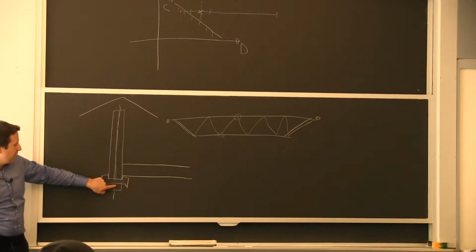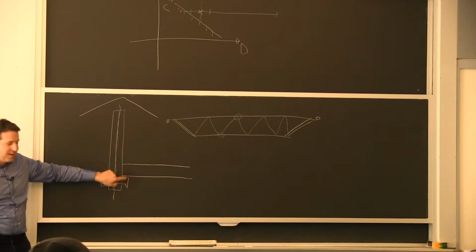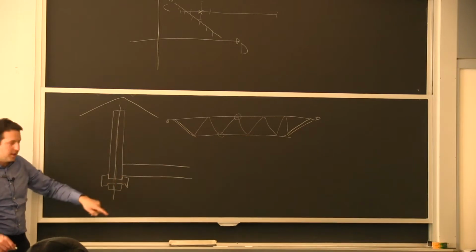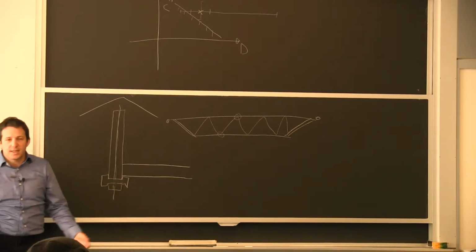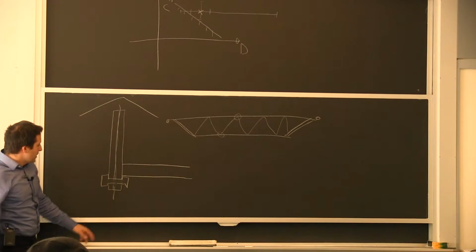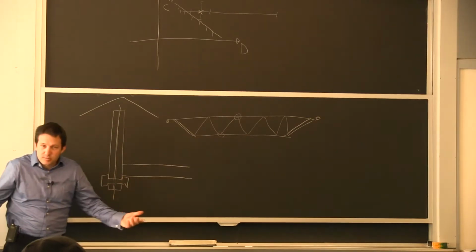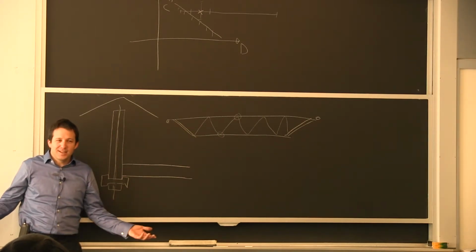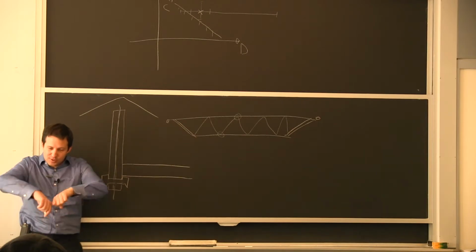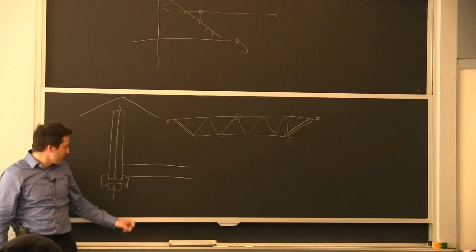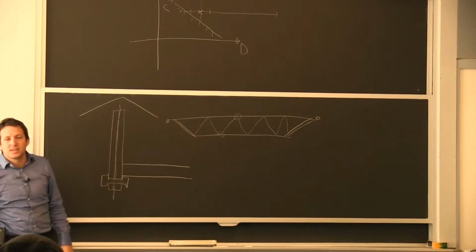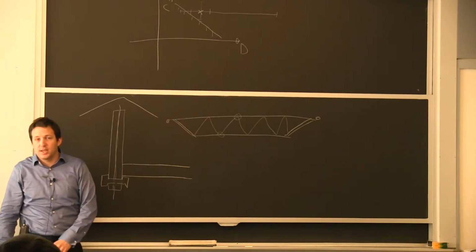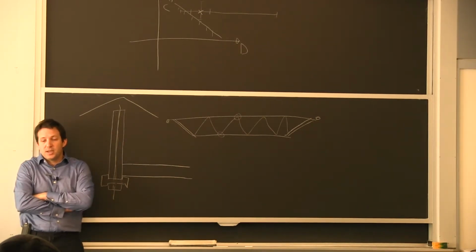Now it turns out this plate was only half the thickness of the chord, and the distance was too big, so they started deforming the end flange here, and it started opening up the welds, and it had nothing to do with the weld itself. I mean, I got called in because I was the welding guy. And I just said, don't expect anything more from the weld. If you just pry it open, yeah, it will fail. So the initiation was the bending of this end flange, but it was a decision of the designer, who somehow didn't run the calculation. It was very unfortunate. They had a big loss.